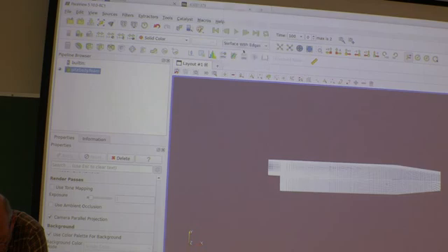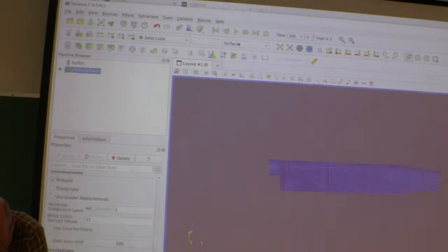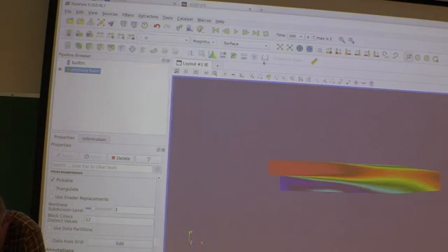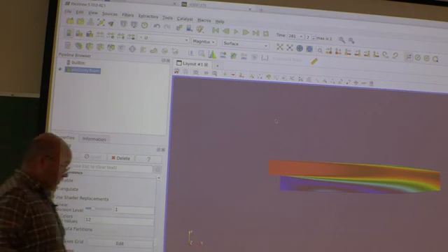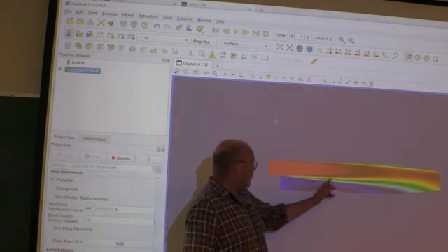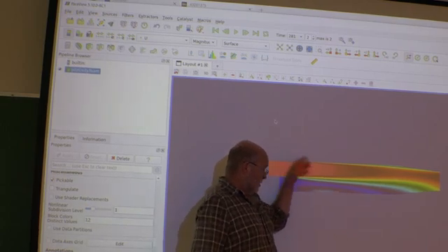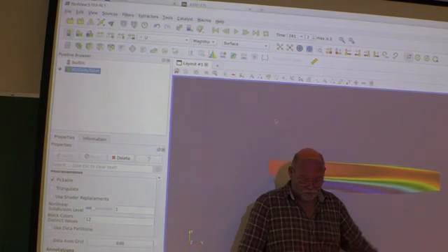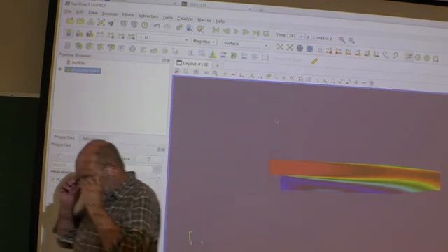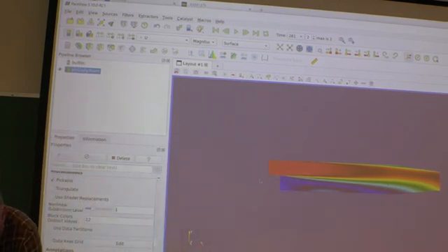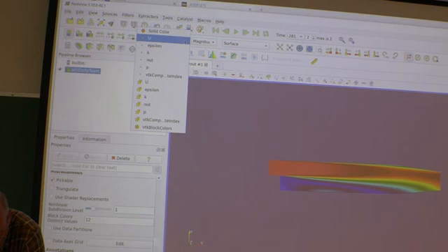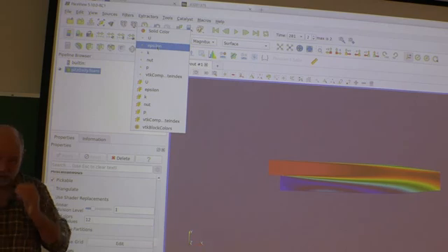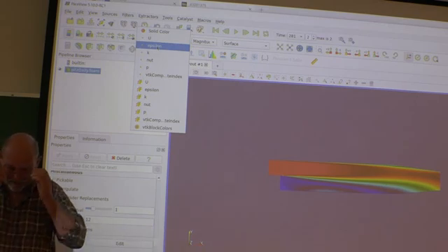Let's go back to surface, thank you, and then have a look at the velocity. And yeah, we discussed this one the last time. The steady state solution, yeah, you have one big vortex after the step, and then you have a nozzle and the outflow. Let's have a look at some of these turbulent quantities. They should be automatically uploaded here, depending on which turbulence model you have chosen.